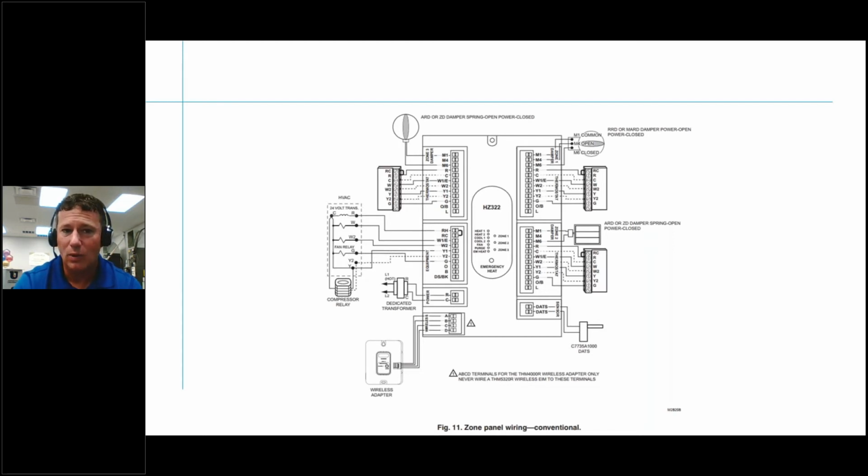But that's not what our industry is moving to, right? We all know what's happening with our industry. We all know the purpose of Daikin, why they came to the United States, is to inverterize the United States because of the efficiencies of these units. So we are moving into variable capacity, variable control, modulating, and communicating. So as good as these zone controls are for conventional zoning, they don't do anything for the communicating platform.